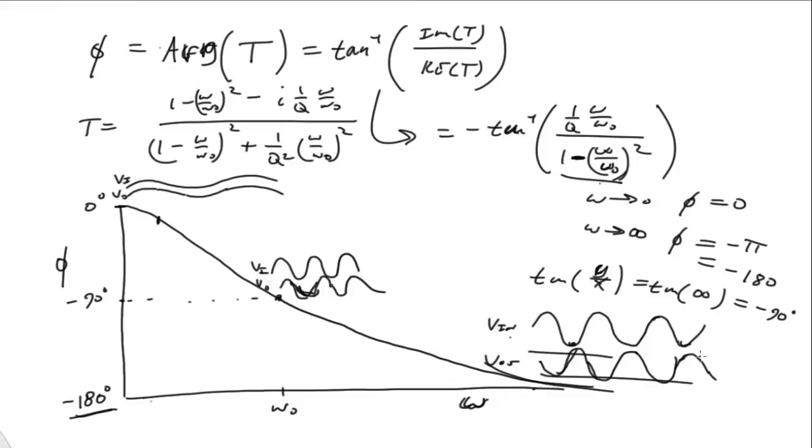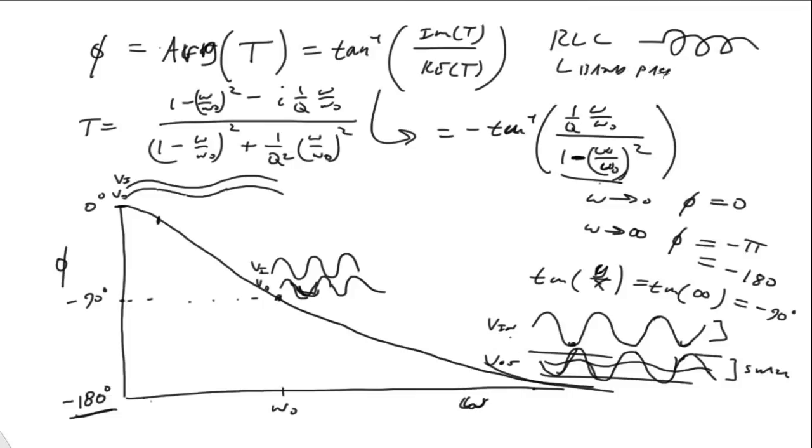And the other thing to note is that the amplitude of this is going to be very small relative to the amplitude here. So I haven't drawn it quite accurately. This actually needs to be like this. But that gives you the idea of what's going on here. So we see with these RLC circuits where we put in an inductor, we can get bandpass filters that admit certain frequencies at a higher amplification than a DC signal.